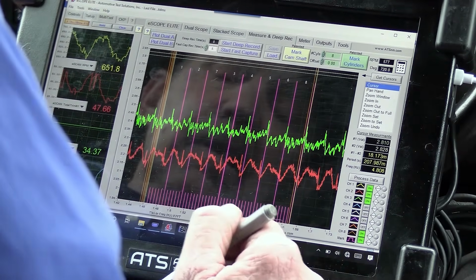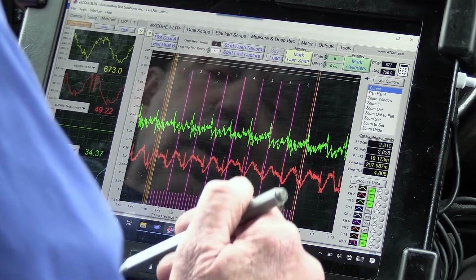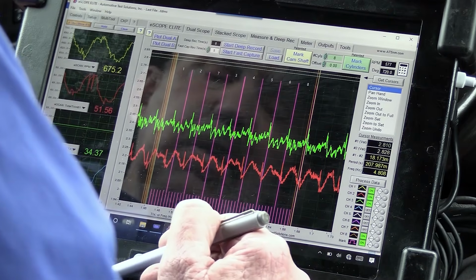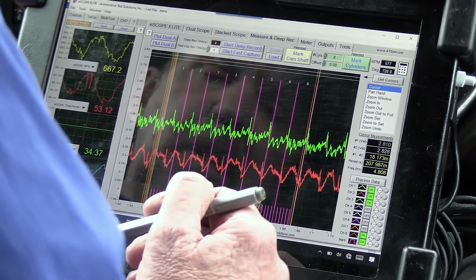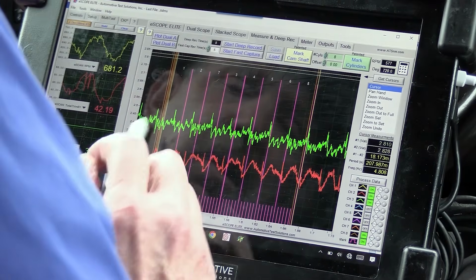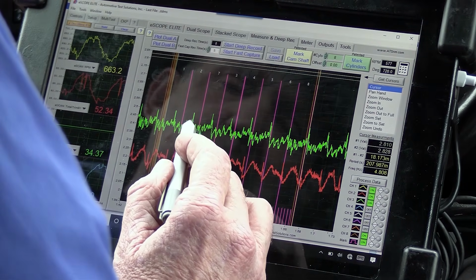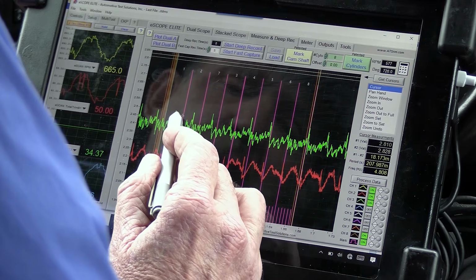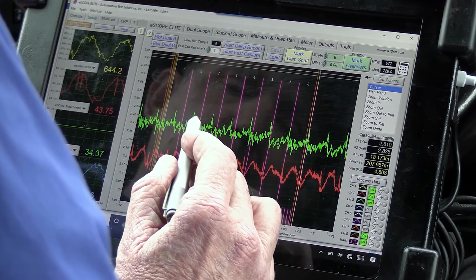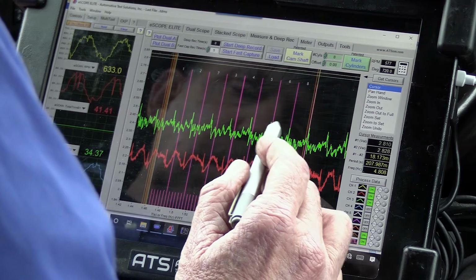But wow, guys, I see something. Wow, look at that. I must have missed that, or maybe it wasn't like this. Maybe it's gotten worse, but I didn't see this before. Do you see where the peak pressure is building? Each one of these is the peak pressure. Do you see how far away this is from the top dead center mark? Do you see how close these are?